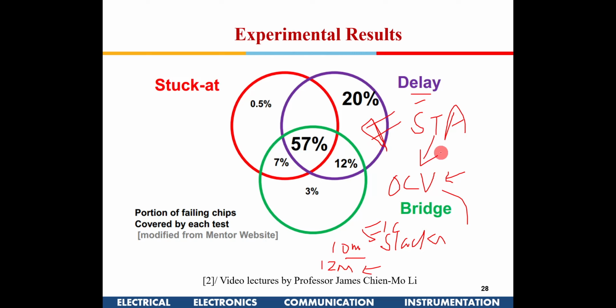All the tools, like PrimeTime and things like that, let us set that percentage. If you are not very confident about your fabrication process, that is given as a variable to you. If you are very confident, say you are fabricating at 180 nanometer technology, which is a very robust technology as of now, then you might want to give only 5%. You might want to cater 5% for your OCV variations in your timing analysis. But suppose you are making a circuit for 7 nanometer, you might want to cater 20% in your static timing analysis,